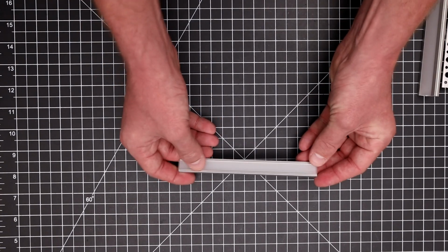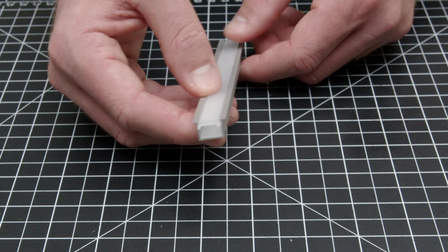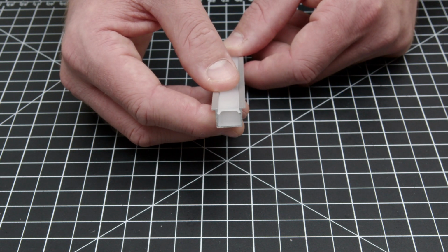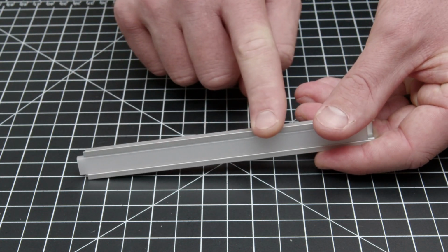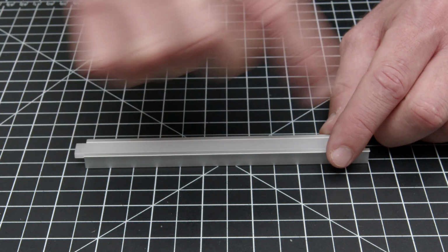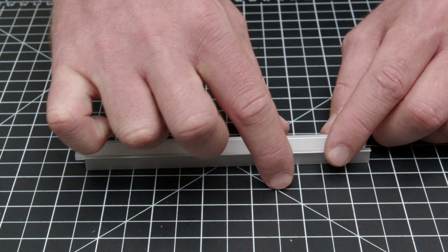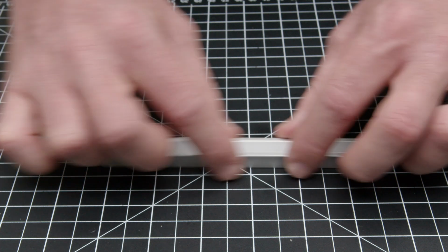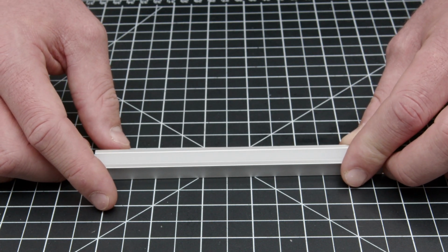So we have what would be more traditional recess, where you have the flanges on the side. This is one of our more indiscreet, minimalistic form factors, our slim recess channel. Okay, and if you ever wondered why you have these flanges on each side, that's because when the contractor is doing the mill work and routing out into the wood, if they accidentally make it too wide, the flanges help hide that mistake and still sit in there with a nice form factor and look really good.